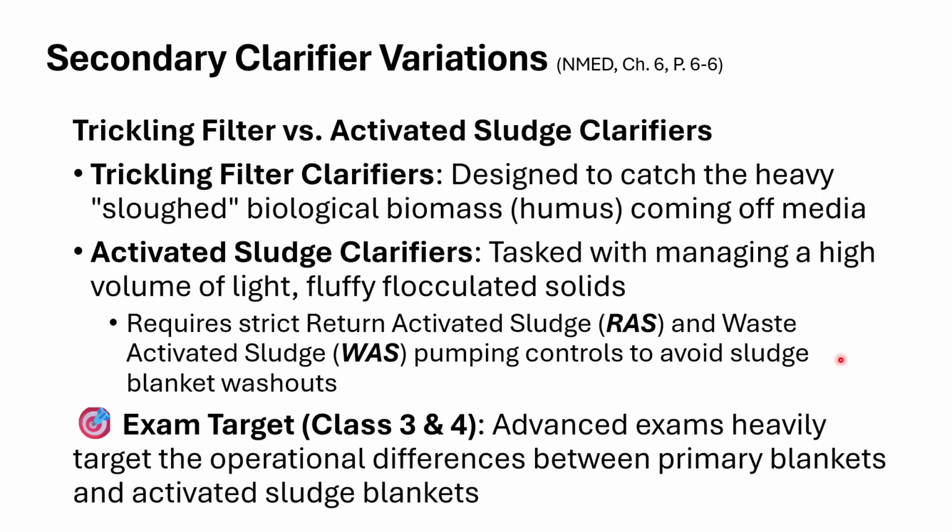We also have an activated sludge clarifier, and that's similar to a certain extent to a primary clarifier, only we're introducing, like I said, heavily concentrated dissolved oxygen into our wastewater along with microbes, and we let them hang out in that secondary clarifier where those microbes are going to chomp away at that waste.